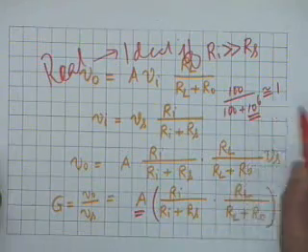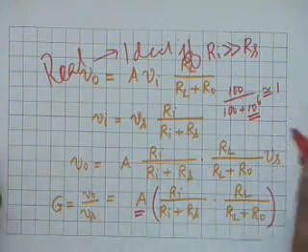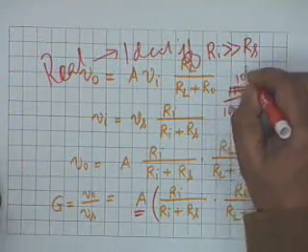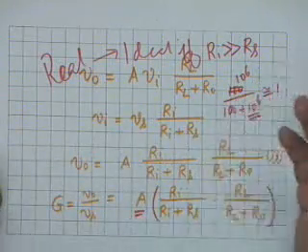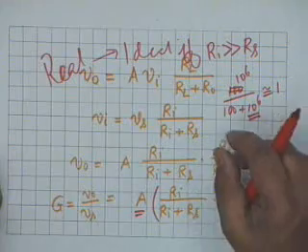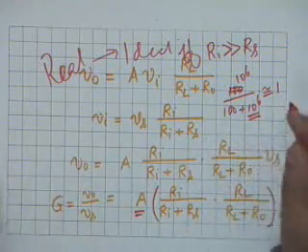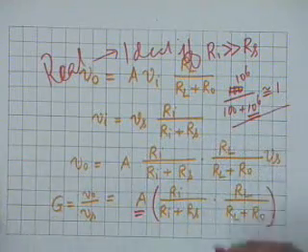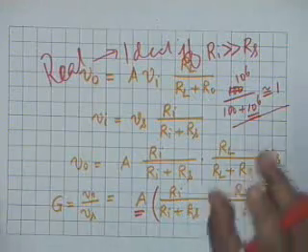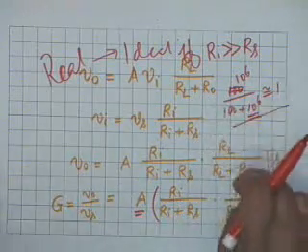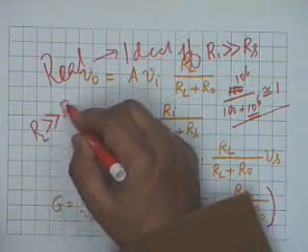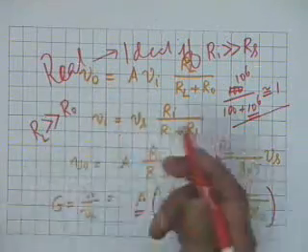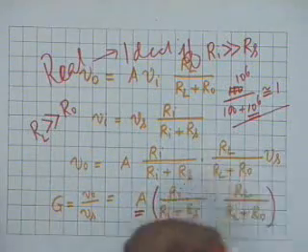Oh, I beg your pardon. It is 10 to the 6 in the numerator divided by 10 to the 6 plus 100. What is 100 to 10 to the 6? It's nothing. And therefore, this is approximately 1. Similarly, what you need is that the load connected to the output, RL, should be much larger compared to R0. Once again, 1:100 for example is good enough.